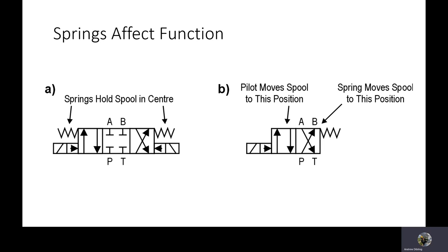This is a pilot valve because you see the little arrow indicating pilot fluid coming into the device, and it's a hydraulic valve because the pilot fluid is shaded in. Spring return, so it's either one position, the other position, or nothing happens in the center with this one. If it's actuated in one way with fluid pushing from the left, P goes through to A, B goes back to tank. If it's actuated from the right-hand side, pushing left, you'll see that P will go to B and A will bleed back to tank. And of course, if I don't have anything triggered, it will return to the center position.